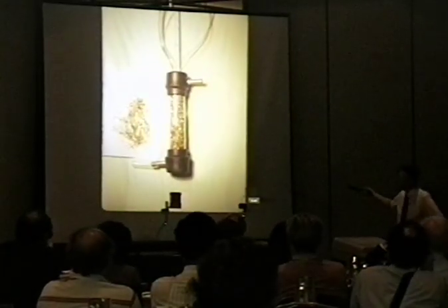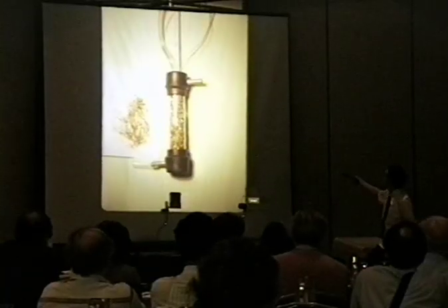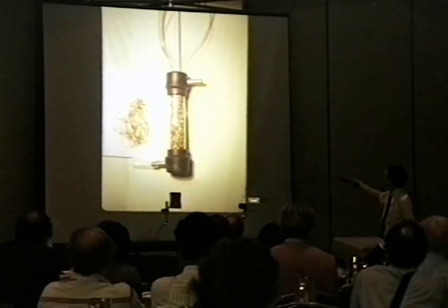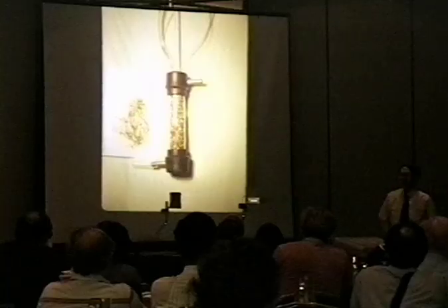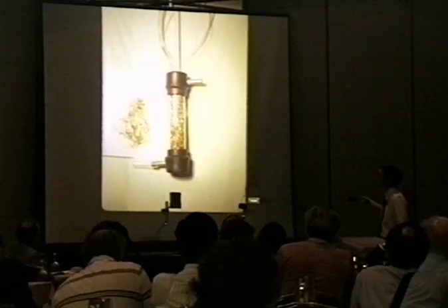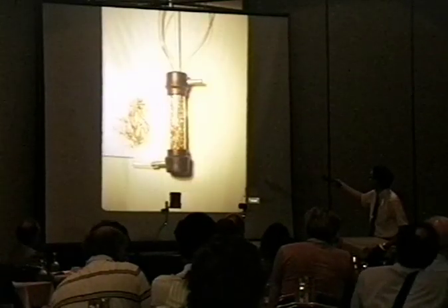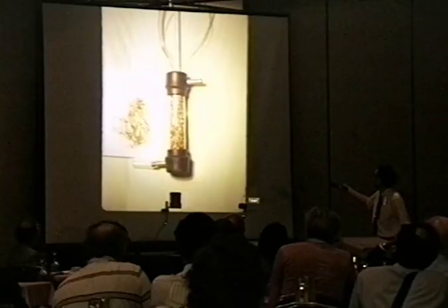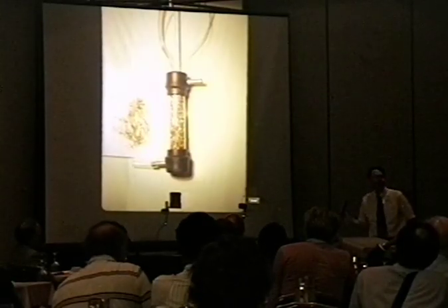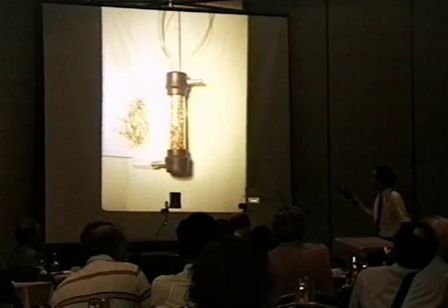Those side pieces, well, maybe I should back up a second. These areas right there are actually widened pieces that I've packed with copper, that I put the thermocouples in there. I actually use a mercury thermometer. I believe in mercury thermometers. But at any rate, thermistors and thermocouples are really bad. Thermocouples are bad at RF. I pack this. The idea is that when the water flows through there, I am averaging out over a larger volume, and I don't have to worry about the laminar effects on the calorimetry. That was advised by Hayden Burgess, who said, what about those laminar flows?